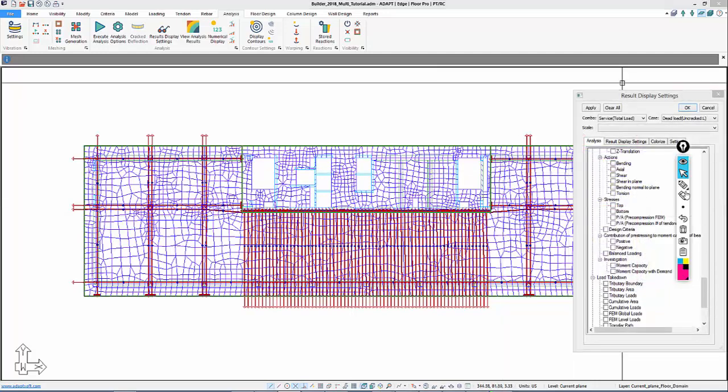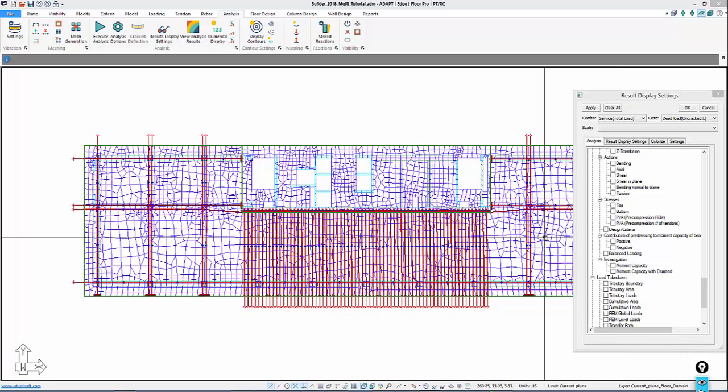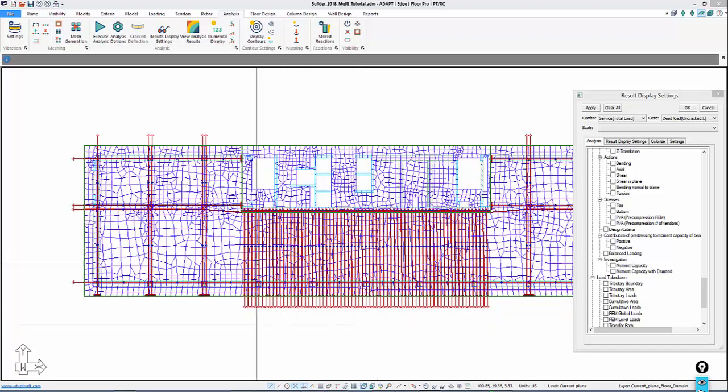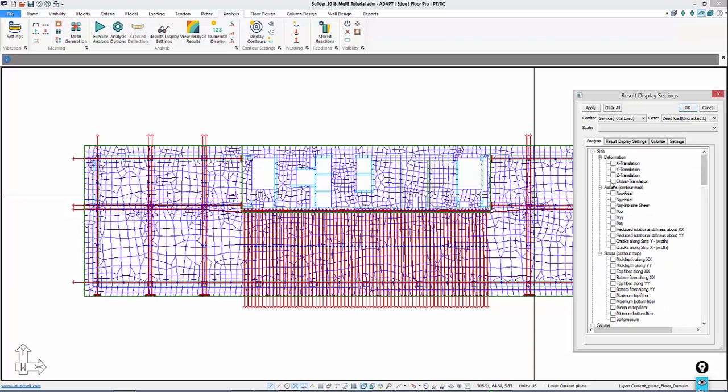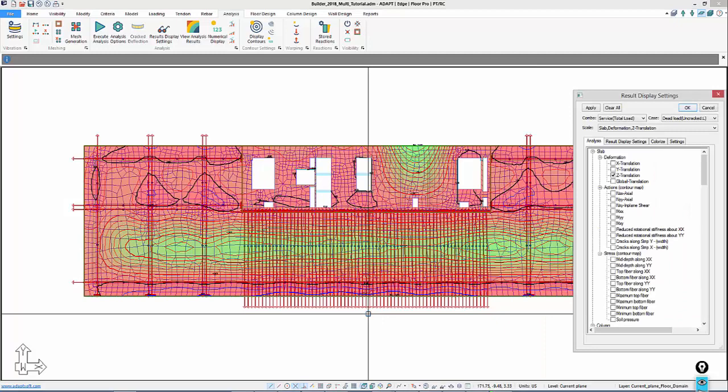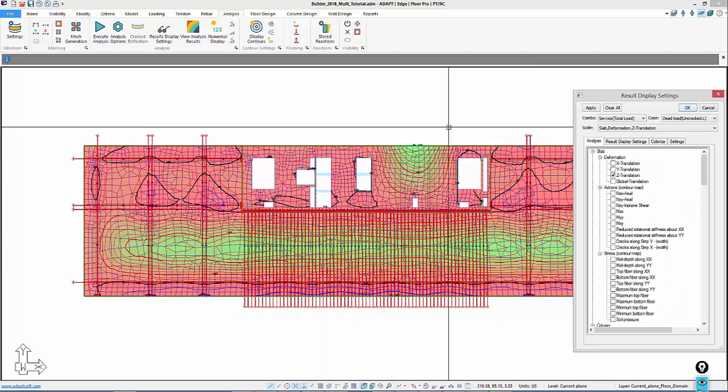So initially we looked at the deflection under self-weight only, and it was roughly 3/4 of an inch. That was without any post-tensioning. If we just take a quick look at the deflection under service total load with PT and with loading, we might be able to estimate where we end up in terms of long-term deflection just by using a kind of a gross multiplier. And you can see that the max deflection is still out in this region.